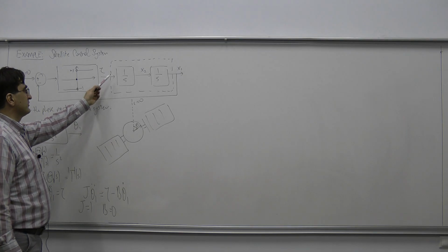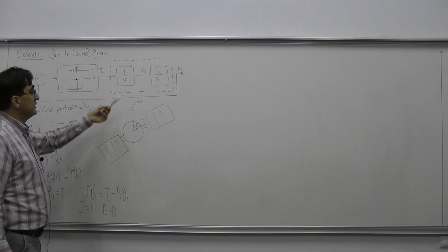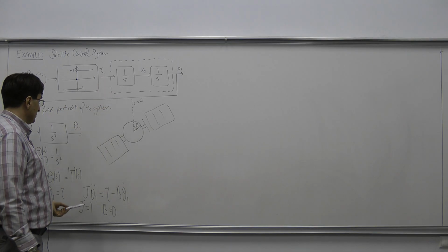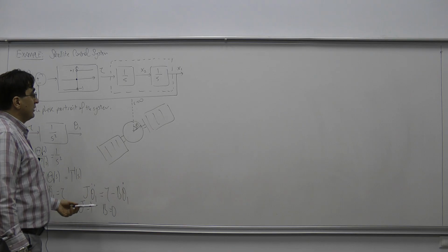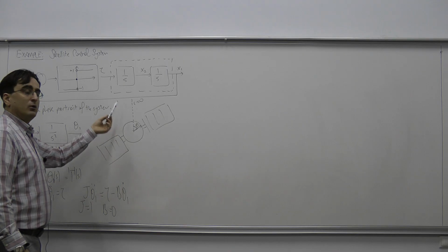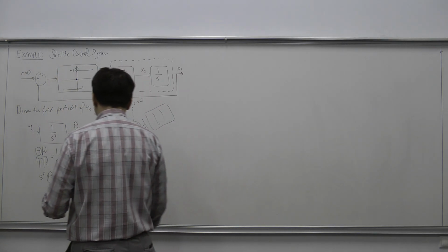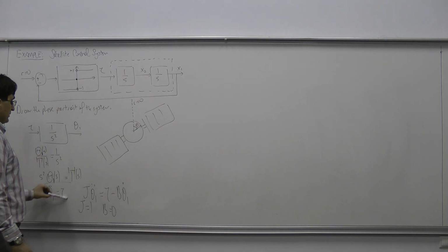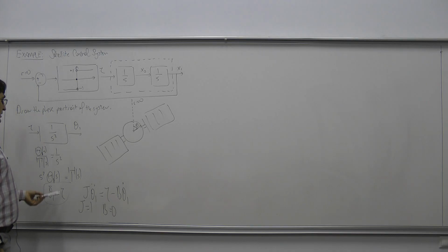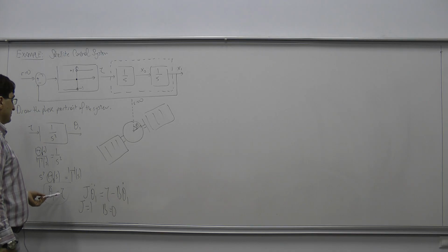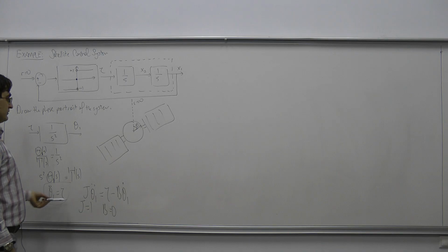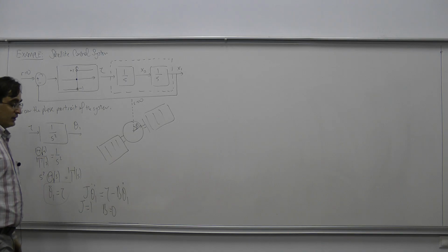Of course, there can be some scalings here. If the inertia of the satellite is not equal to 1, this is just a simplification. And we assume that there is no friction in space. That means that we're going to have just a simple double integrator. So the double integration of the torque applied onto the satellite body is going to be theta 1.